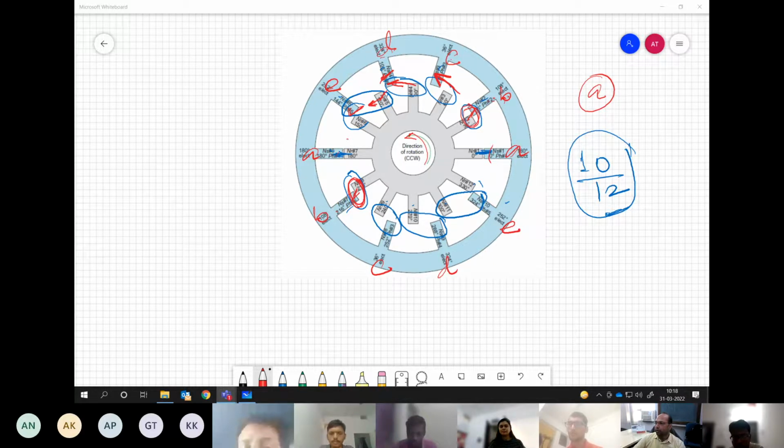So this is what I meant by grouping of the coils together. Whichever pole positions are looking similar, you group them together and make them one phase. That is how you will be able to differentiate how many phases there are. So this is something like a 5 phase 10 by 12 SRM.